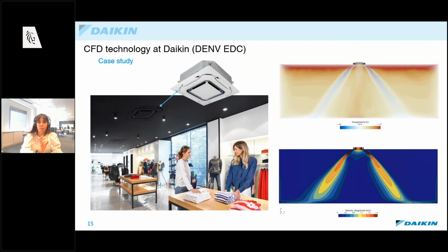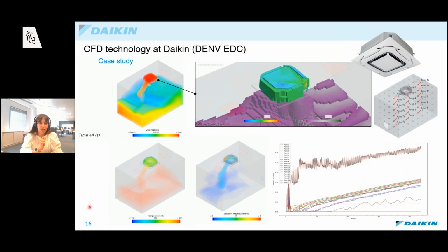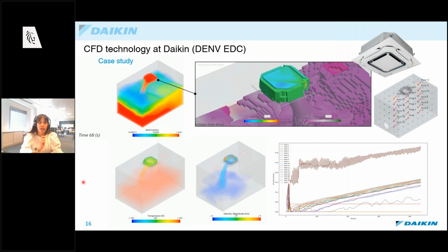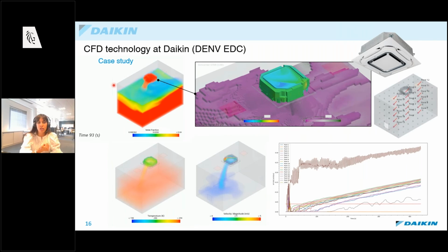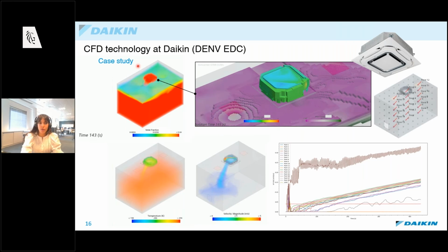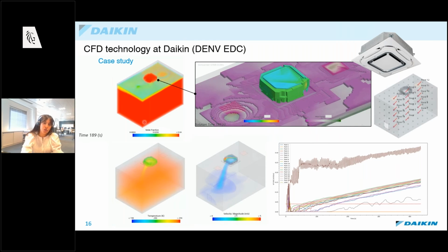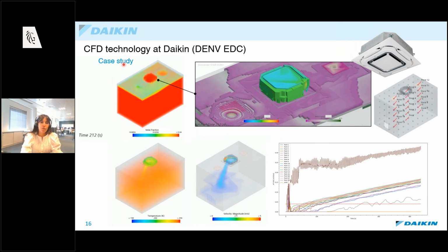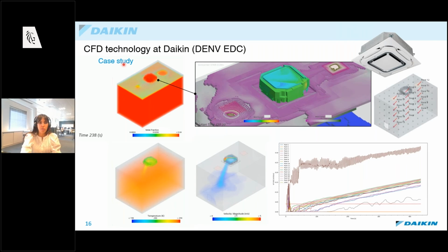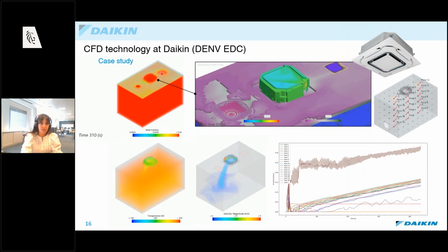where we would have to include the multi-component model. For example, here we can see already the results of a leakage simulation. Normally, what we do here is that we need to include the multi-component model, we include the ideal gas model, and we simulate the real conditions of the specific refrigerant that we would want to study during a leakage case. We put the correct temperatures, the correct pressure. Also, for example, if you see here, this would be like a normal room. You can see there are 2 vents here, and this means that the ventilation system of the room would be also working.